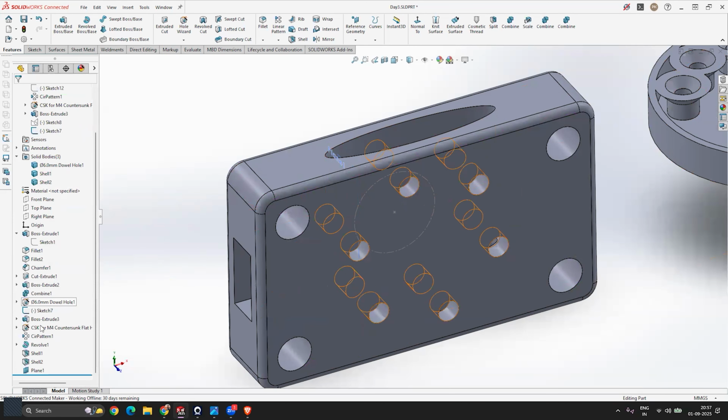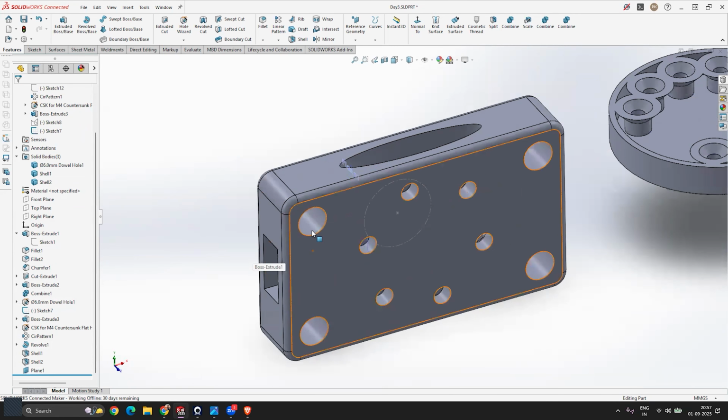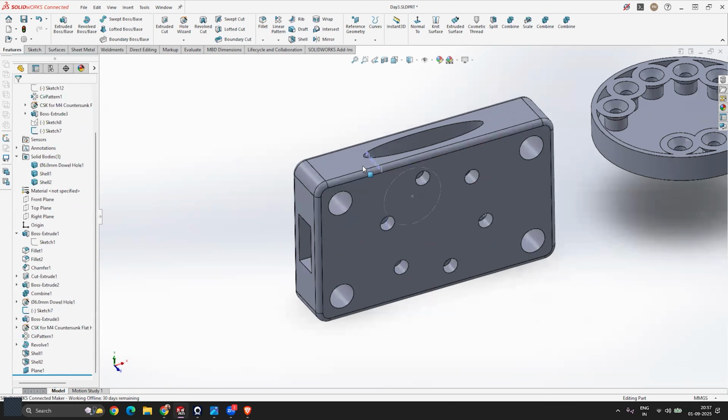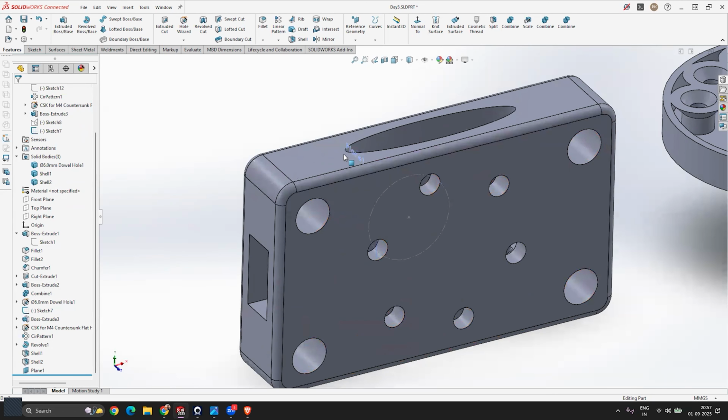And the moment you click on finish, can you see in the design history, this plane step also got added, right? Now, this is the plane we created. Here you can see. Now, let's split this body with reference to the new plane, that is Plane 1 that we created. So activate this tool called Split Body tool.